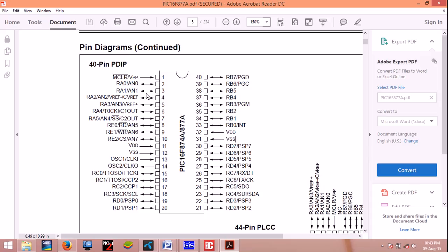Here you can see the 4 types of ports: A port, B port, C port, and D port. You can use them according to your need. It's up to you which pin you want to initialize and which pin you want to use in your project. In our case, we have to plan first, so I'm trying to use RB0. It's not that because I'm using RB0 you have to use RB0 as well. Whatever you want to do here you can do, according to your own willingness.